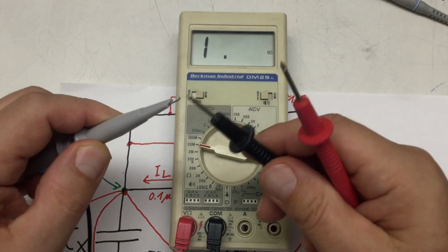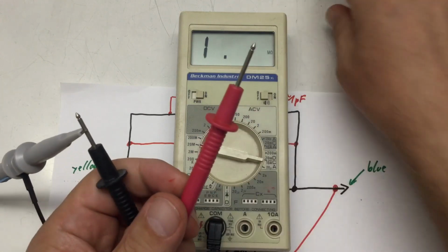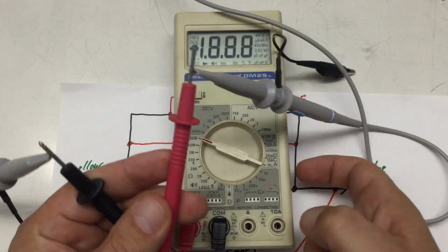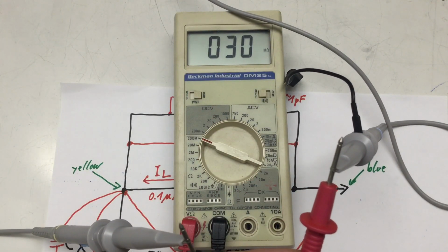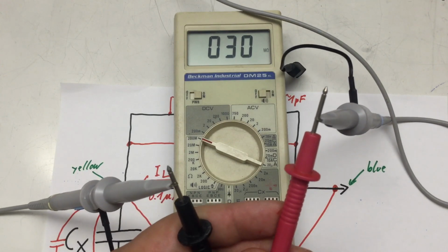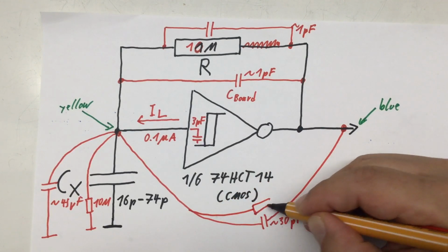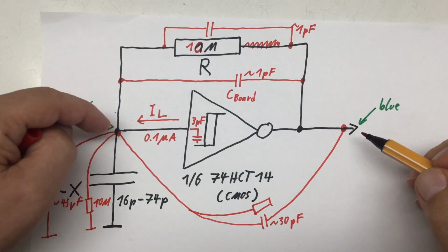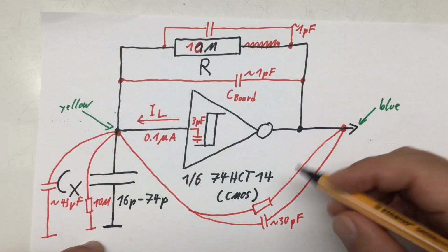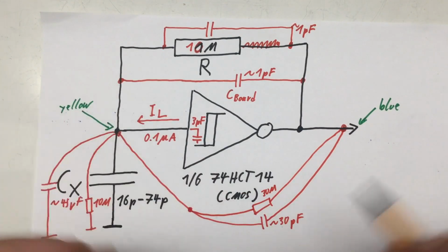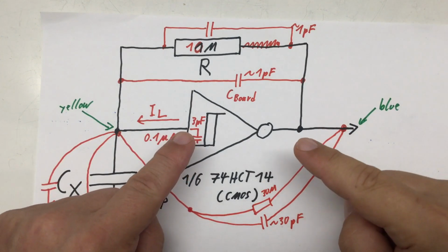And last but not least, let's see what's the resistance between two probes. That should be at least 20 meg. Okay, that's about 30 megaohms. So we can almost forget about that. Nevertheless, having another resistor connecting our input with our charge point of about 30 meg. So all in all, the oscilloscope messed up our oscillator quite good. And now let's continue with the experiment.